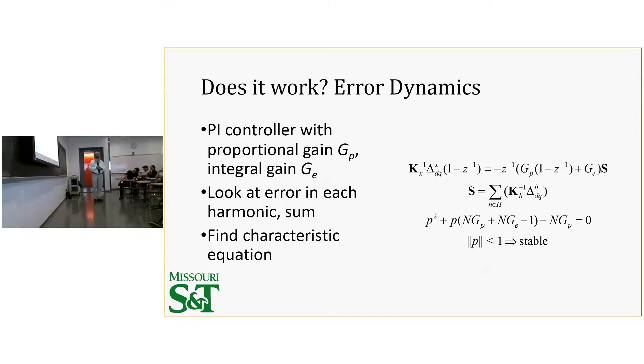No, because it depends on your relative proportional integral gains. And in actuality, I included proportional gain here, but don't usually use it. Usually you set it to 0, in which case you'll see a pole at the origin and then another pole.